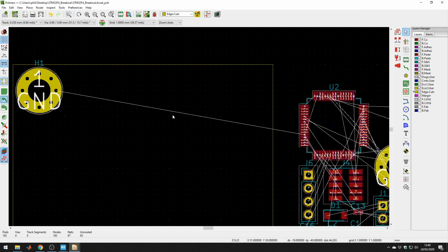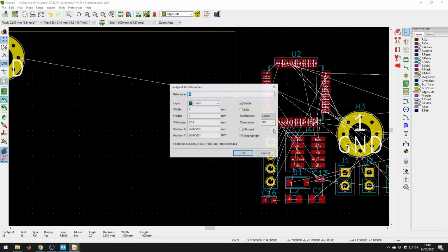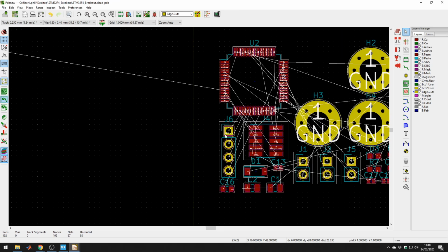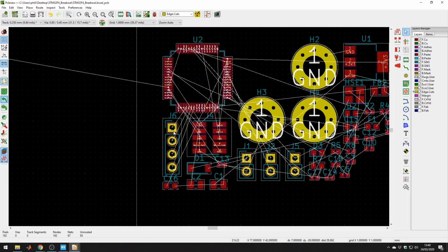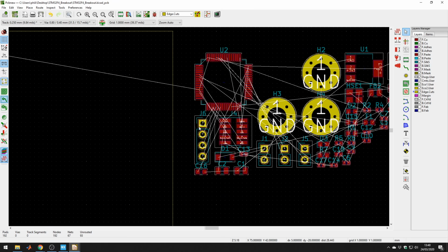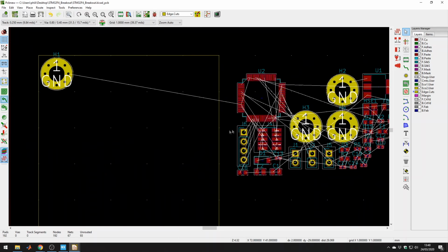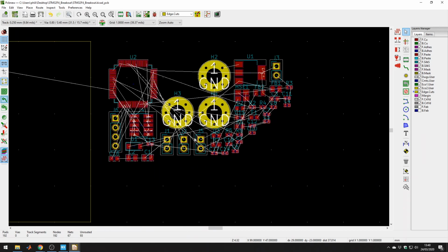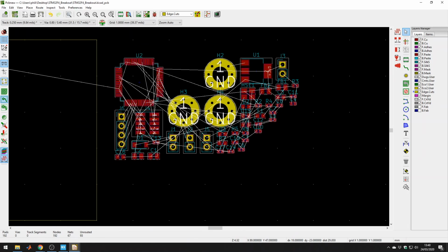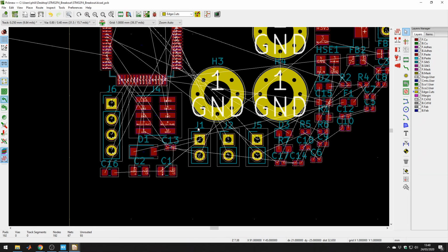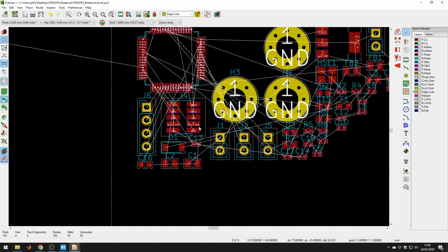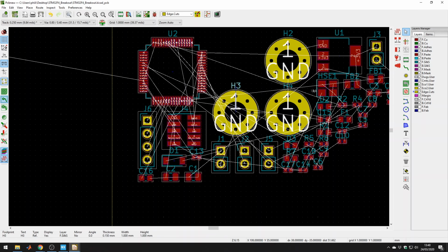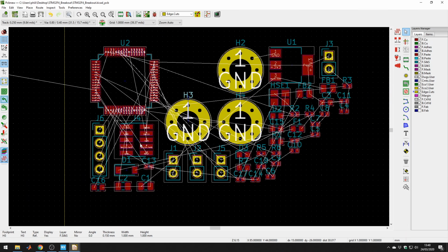I prefer to not have these kind of designators on the Silkscreen. I don't think it looks very nice, and I tend to add my own designators. When I assemble it myself, I tend to just have KiCad open and do it in parallel. Also, these aren't necessary for the assembly with JLCPCB. You send them an extra footprint positioning file, so you won't need these, to me, quite ugly designators.